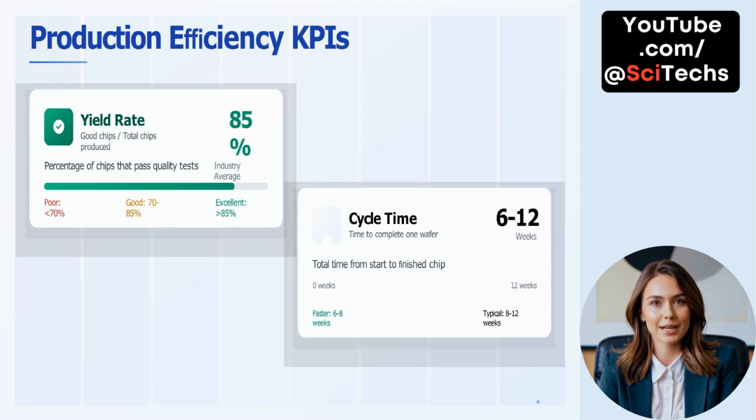Production efficiency KPIs. Production efficiency KPIs are key to understanding how effectively semiconductor manufacturing lines are running. One of the most important metrics is yield rate, which measures the percentage of good chips produced out of the total. These are the chips that successfully pass quality testing. A yield rate under 70% is considered poor, between 70% and 85% is good, and anything above 85% is excellent. The current industry average sits right at 85%, setting a high benchmark for operational excellence.